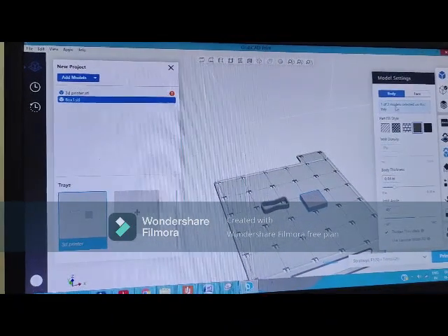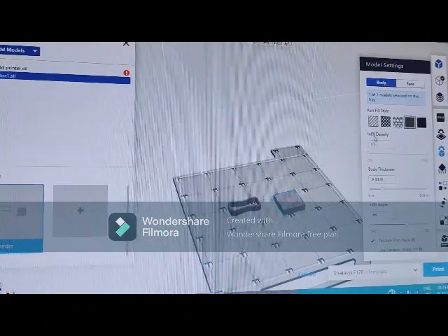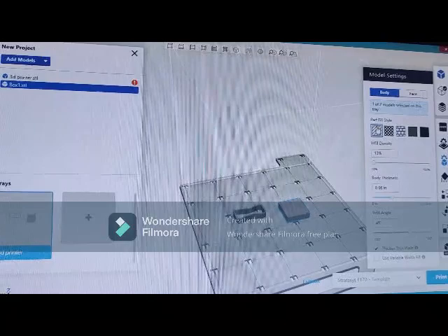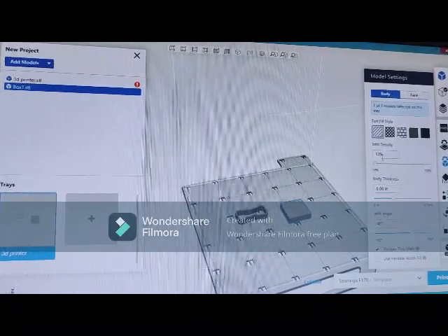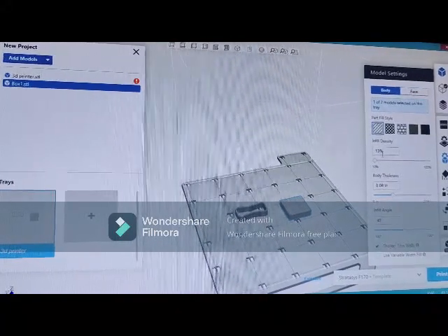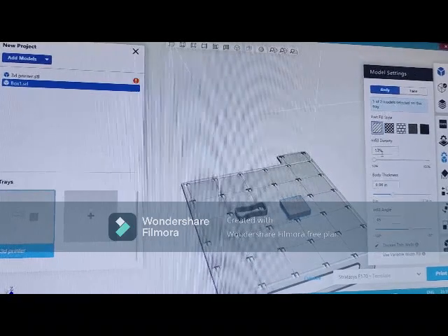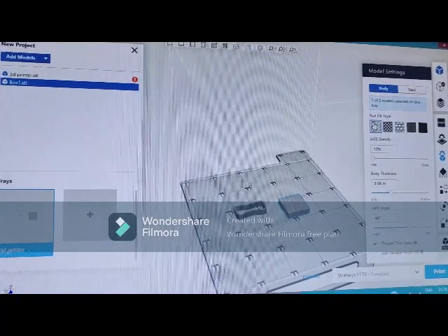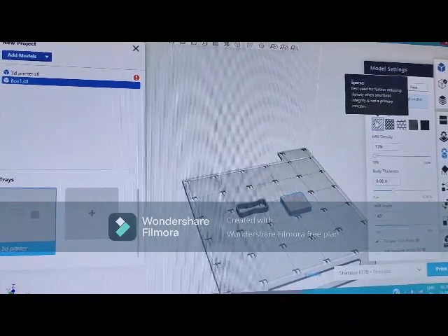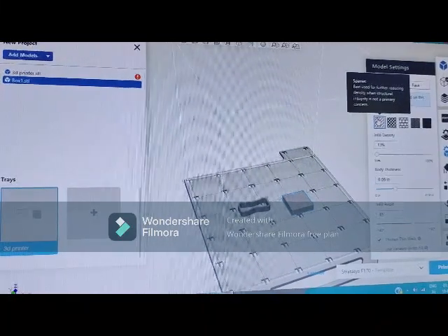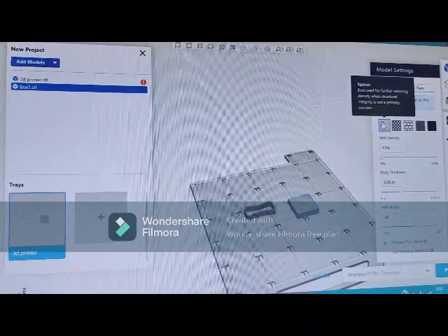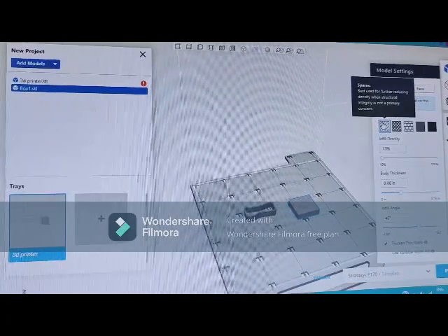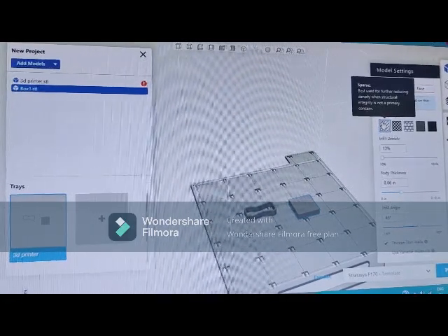This one we have a section here, that is the model setting. Here we can set the filling style, which is the infill. The infill density will be 13%, so the overall geometry will have only 13% of the material, and we can choose the pattern here. It is written here, best used for further reducing density, so density will be less when structural integrity is not a primary concern.